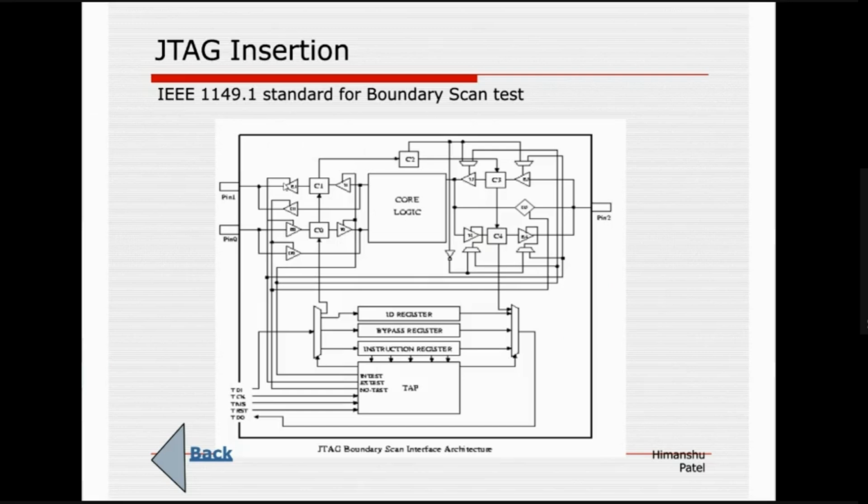Never mind that. These people introduced that you need some logic and an FSM to control what's happening inside the IC to the outside world, so that you can gain access directly from the pins. You will have more flexibility through the proper FSM. If you have an FSM, you can test the interconnectivities between multiple blocks inside your IC. That's the work of JTAG.